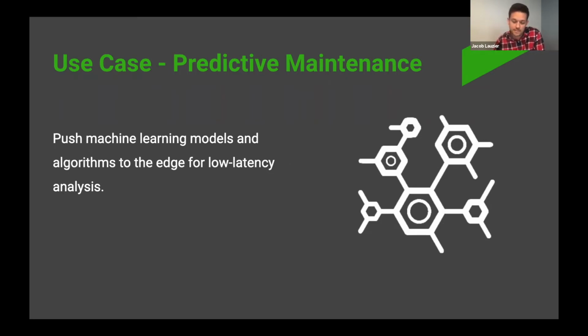It's really common for manufacturers to set their tool life counter on their machines far below the full life of the tool. And by trusting a system to tell you when the tool is actually at end of life, you're able to get a significant amount more parts out of a single tool.